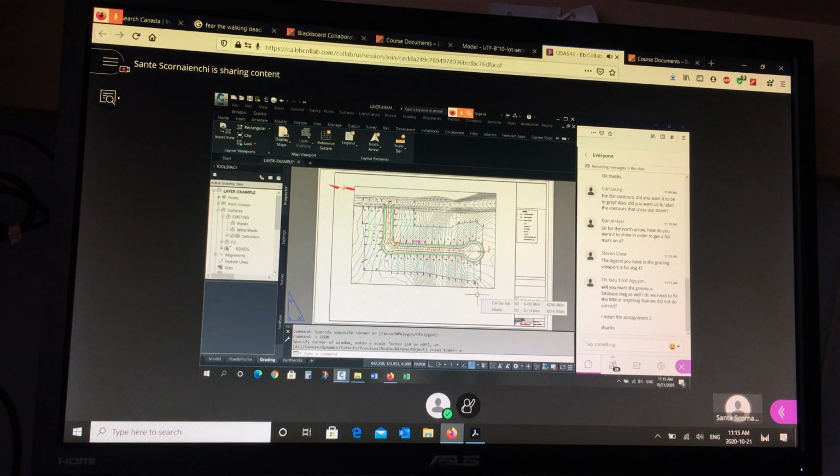Right? So it takes a little time. MED next semester is going to be very familiar. A lot of what we're doing here, you're going to do again. The subdivision's different. The topo's different. But you need to create an alignment, lay everything out in plan, design the profile, model the corridor, get your front lot runners, input the pipe design, and so on. It'll be the same process, just different starting conditions.